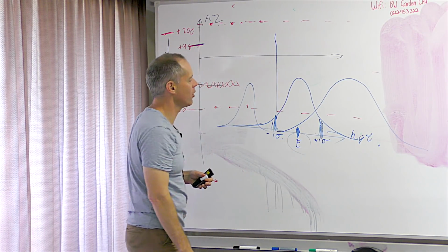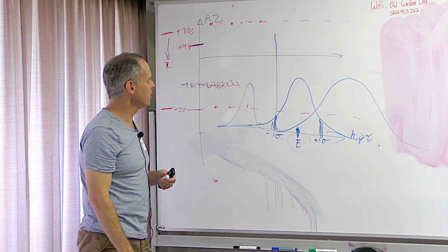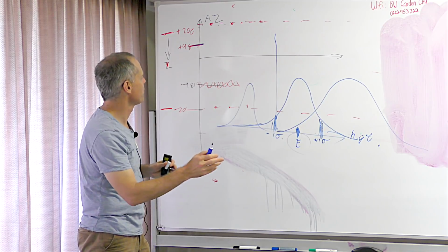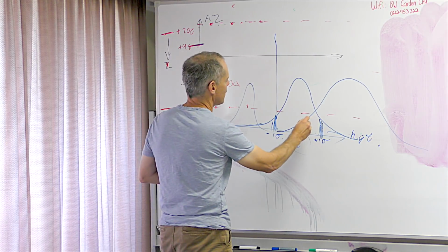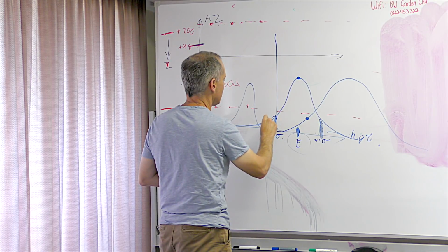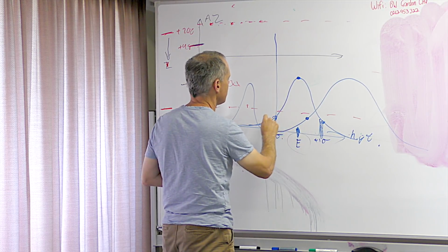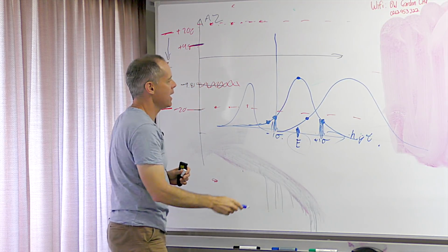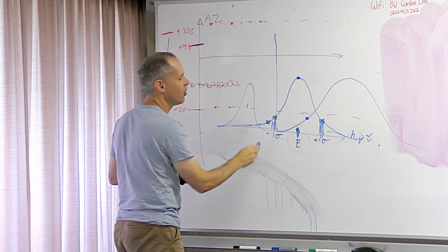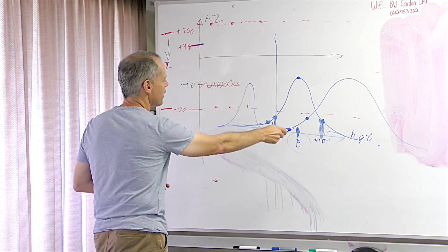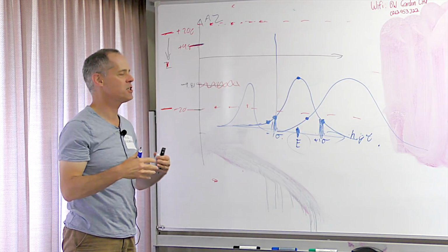What the UKF does, and the mathematicians are going to cringe here, is it takes sample points: an expected value point and sample points that represent points on the distribution curve, and it propagates those points forward in time, and thus it's better able to accommodate non-linear operations.